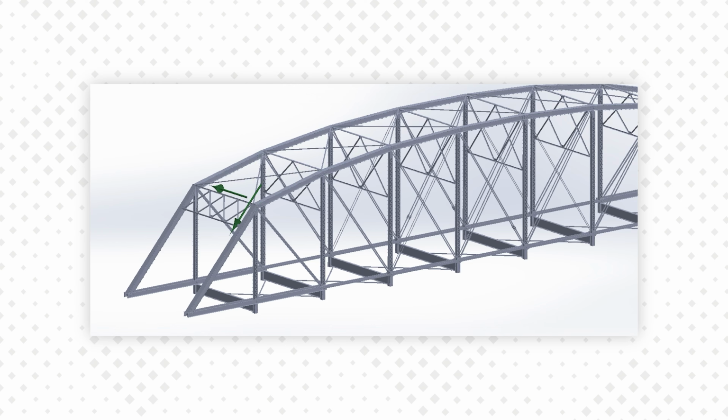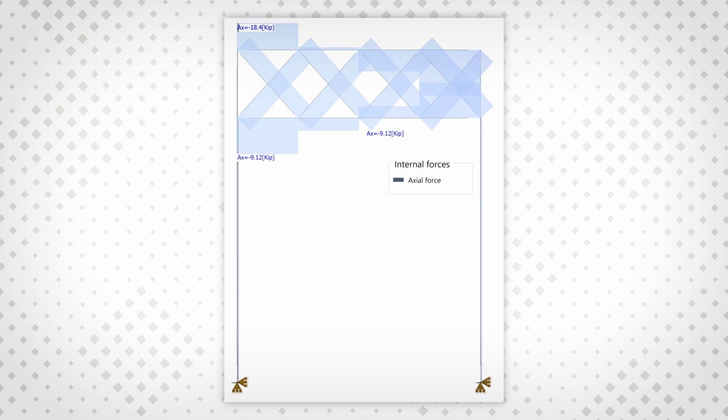Remember Newton's third law? On the upper level, the wind forces make their way to the portal frame on each end of the truss. The portal frame resists lateral forces through bending in the posts, which are the primary truss end members, and tension and compression in the connecting truss. This allows vehicles to pass and loads to flow around the opening.